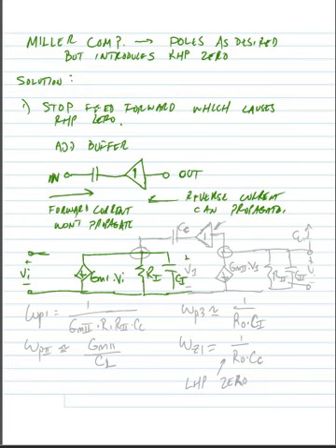We develop a voltage across C1, which we'll call V1. We have the second stage, which has a voltage dependent current source, GM2 times V1. And of course the output resistance and capacitance from that second stage, R2 and C2 respectively. And we take our output from the second stage, Vout. And we might have a load capacitance tied to the output as well.